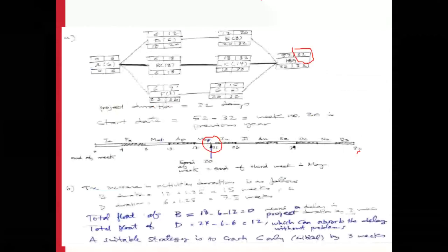So in this situation, we are talking about that we started work, but activity B and activity D had to face certain time delays, and as a result, activity B could not be completed in 6, but with a 25% increase, this will be 7.5, whereas this activity, which was previously taking 12, would now take 15 weeks. Now we see that this activity is the critical activity.